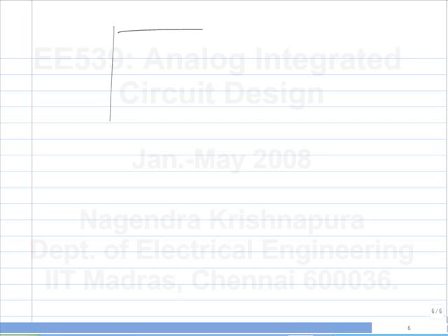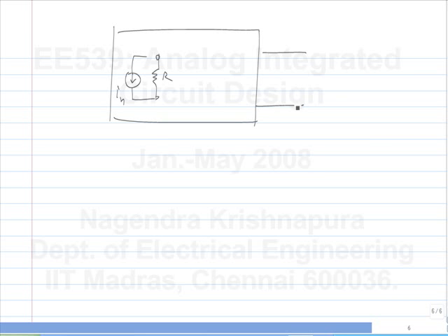So you have some circuit, and every resistor has been replaced with a resistance in parallel with a noise current. And let's say, just for illustration, that the output of interest for you is some V out. So how do I find out how much noise is there in V out because of this IN? It is like any other source in the circuit. So I just disable all the other sources and I calculate V out by IN. I have used uppercase here because these things could be frequency dependent.